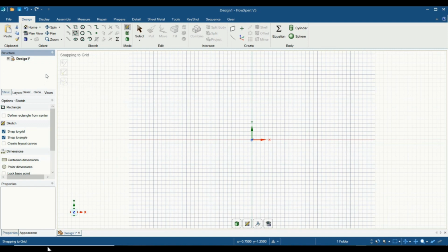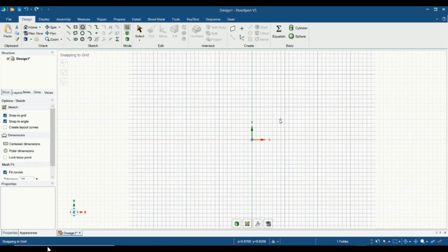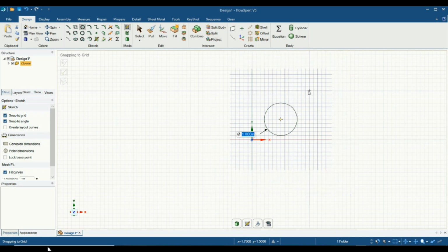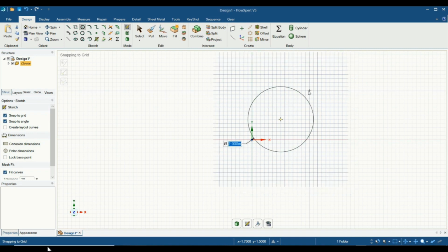A standard circle is easy to draw. Click on the Circle tool and move the mouse cursor to the design view. Click to set the position of the circle center. Clicking the mouse a second time sets the diameter, which can be modified using a parameter box. With the Circle tool, the only parameter to change is the diameter. The Tab and Enter keys can be used to view any changes of parameters. Pressing Escape or clicking in the design view ends the operation.